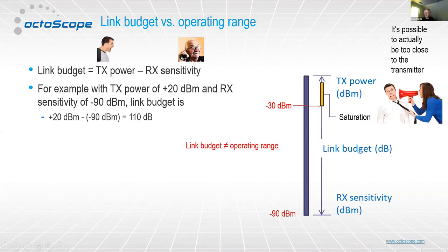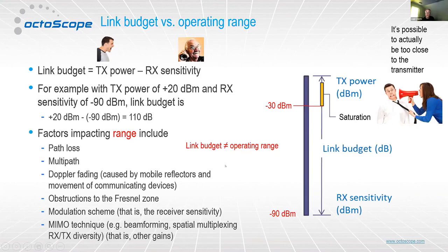So there's what's known as an operating region between the highest level signal that a receiver is built to handle and the lowest one. And in Wi-Fi, the range is something like this: negative 30 dBm at the top side, down to in the neighborhood of negative 90 dBm at the bottom side. So the factors then that will influence the total range have to do with the path loss that we've hopefully been describing this whole time.